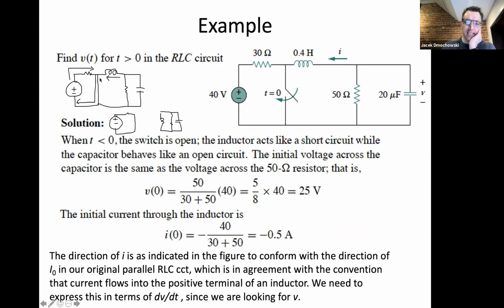And it gets here. It's going to take the short circuit path. It's not going to go through a resistance when it doesn't have to. And so what this means is that these two circuits are completely decoupled. You do not have to worry about this capacitor sensing this battery. It will not sense it. It's as if it doesn't exist.